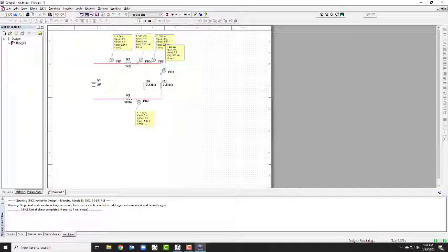But it looks like I got a little problem with voltage. That's 2.54, and there we got 0.935 volts, and then a minus 1.02 volts. Something's not adding up here, so I'm going to stop the circuit, because I was expecting to get the voltages across these resistors, but that didn't seem to happen.